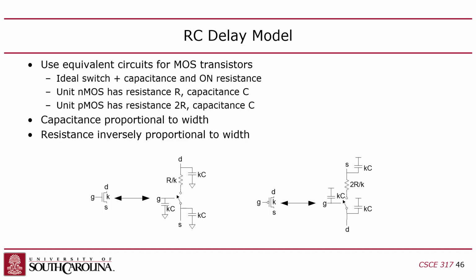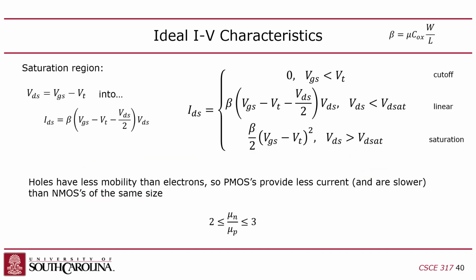In that case, SPICE is going to have a model, and that model is essentially what I showed you, or similar to what I showed you with the IV. This is the model. The problem is that this model is not a linear model. If you have a circuit in SPICE, you have to solve the circuit using Kirchhoff's voltage law, Kirchhoff's current law, and Ohm's law. But the currents coming out through these transistors are not linear.